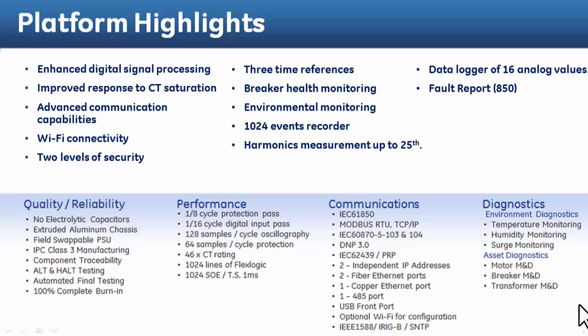8 series platform highlights include enhanced digital signal processing, which is delivered through the enhanced filtering technique and protection path of 8 times a cycle. Improved response to CT saturation and other system transient conditions, which offers an option to operate IOC based on either the fundamental or from RMS quantity.